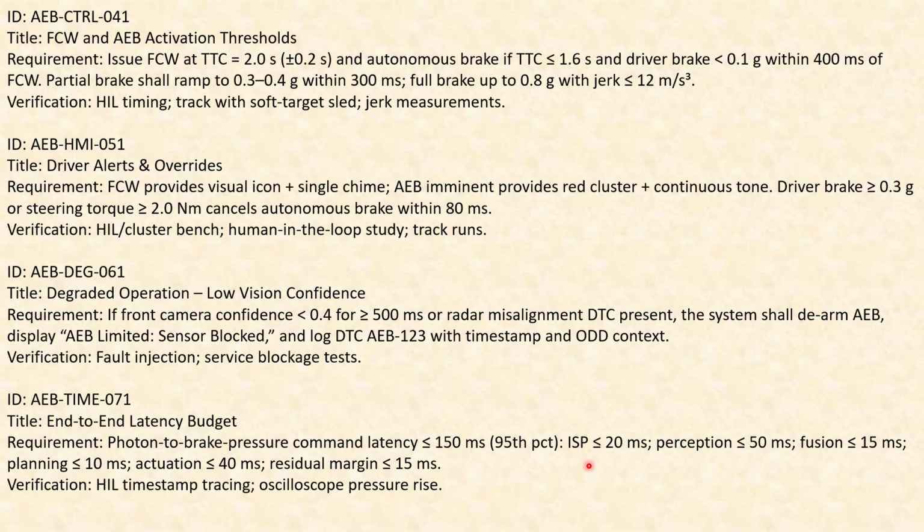Fusion should be less than 15 milliseconds. Planning should be less than 10 milliseconds. Actuation should be less than 40 milliseconds, and residual margin should be less than 15 milliseconds. So if you make a cumulative of all these things, that comes under 150 milliseconds, and within this 150 milliseconds, this many actions are happening. This is verified with hardware in loop timestamp tracing or oscilloscope pressure rise.